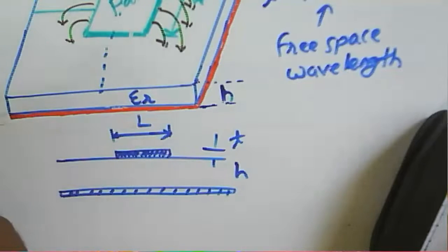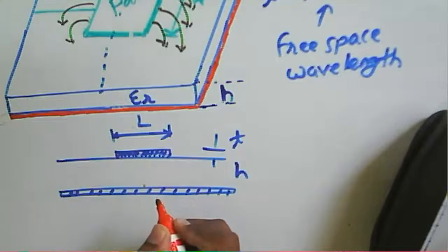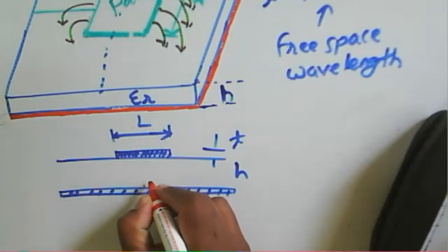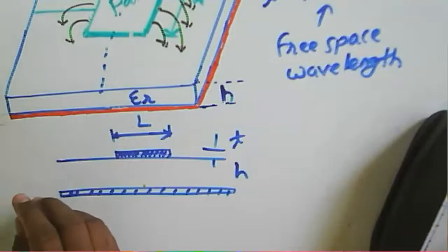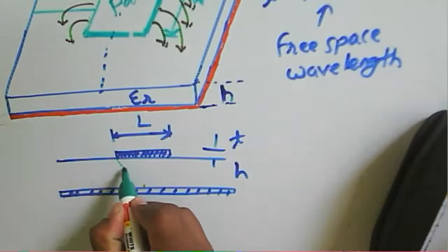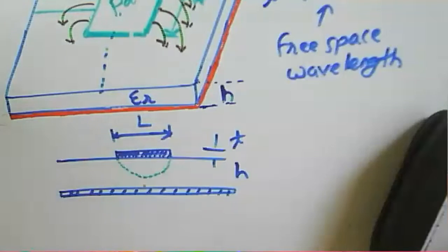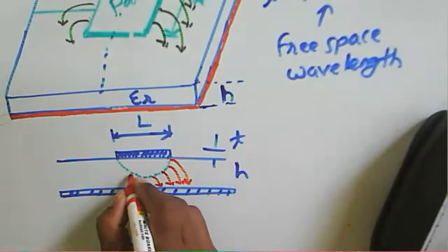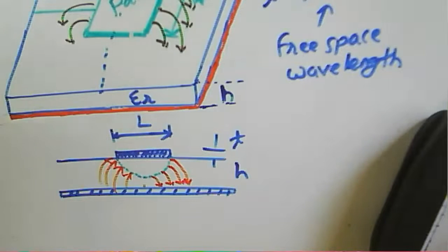If I take a cut section, then the field will be at the center. From the center here, we are supposed to draw the field distribution. So for half of the portion here, it will be different. We are supposed to draw it first. Then we have to find out likewise here, the downward. This one is the upward now because it has two radiating slots.